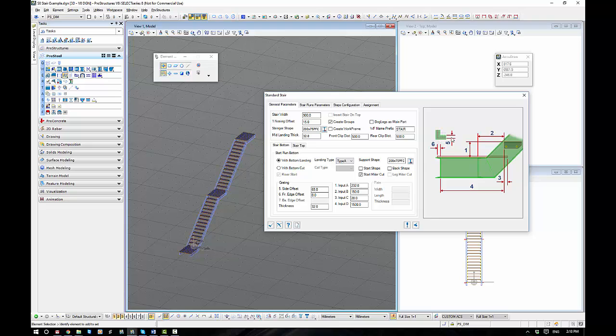Okay, you can see that we can offset all the grating and so forth the way that we always have, but we've probably got a lot more control here now. The key important thing here, I guess, as a user, the grating thickness for the bottom that we use gets added into figure number 1. So essentially, if I've got a 200 PFC, I want the PFC thickness as well as the grating thickness, giving me number 1 here will be 232.